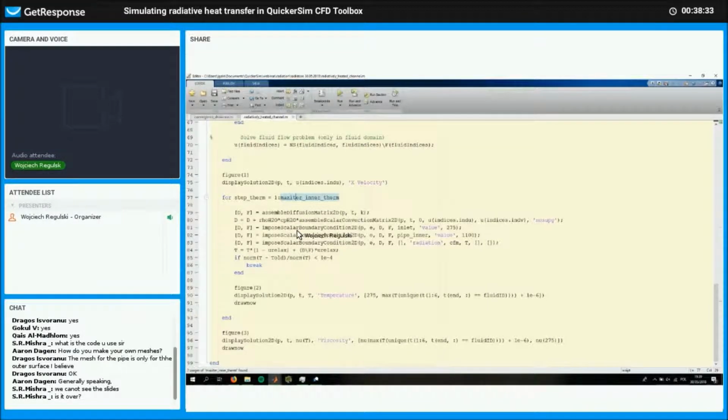If we recall the heat transfer equations, they're linear. So you would think they only require one iteration since they're linear. But actually, radiation is certainly not linear, just because you have T to the power 4, but also because you need to iterate your solution at least several times so the proper surfaces heat up to what they actually should heat up. This is sequential, but I don't think there are any surprises. So this is the thermal problem.